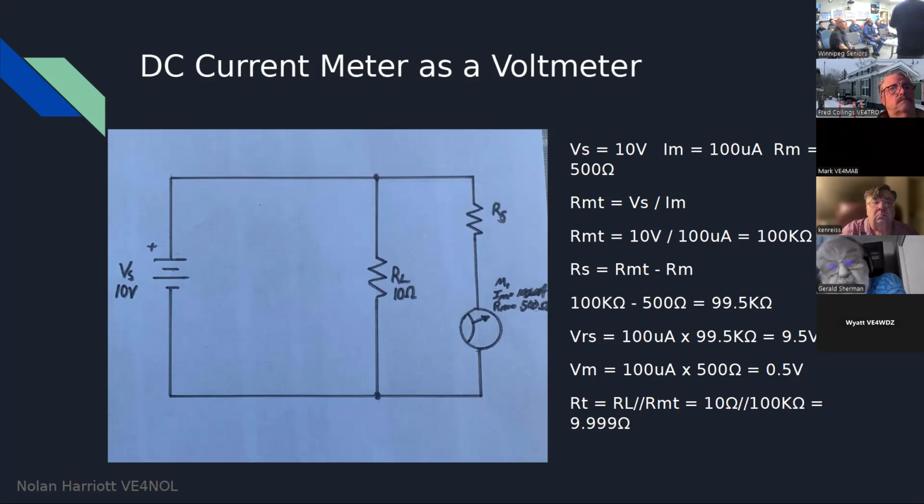I just wanted to touch base on how those are basically designed, so you can see that you are actually changing the circuit by simply putting the meter into that circuit. As soon as you touch your test leads in there, you've changed things. So you've got to think about that when you're reading your measurements and how it is going to affect the accuracy of what you're reading. It is going to change it.